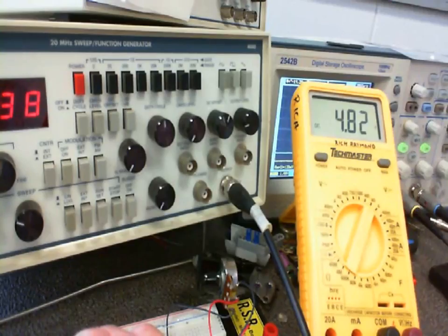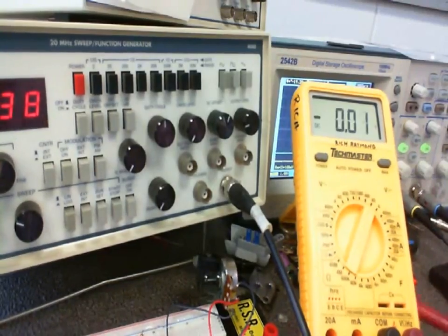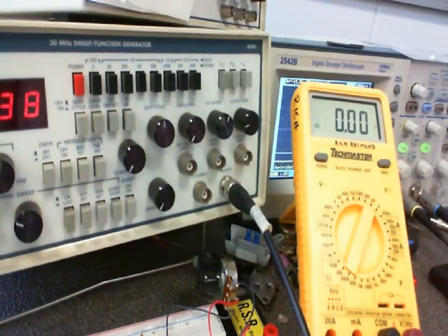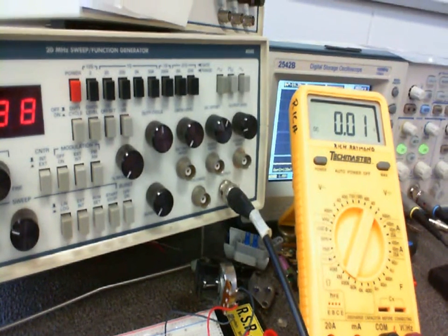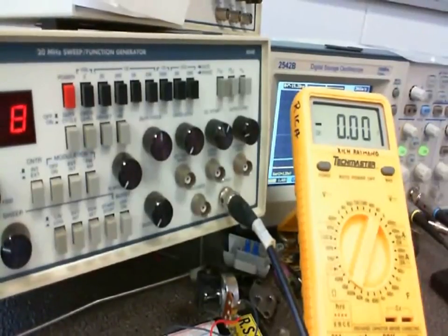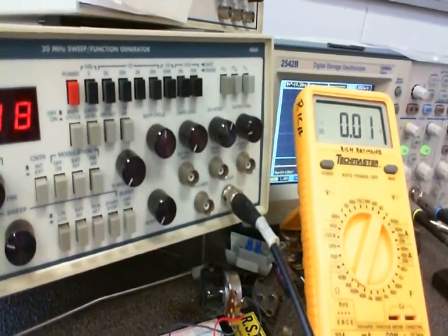Okay. Now what we're going to do is, I've got this heat gun that we use to heat shrink with. And I'm going to look at the collector voltage, which is the collector to emitter voltage, because the emitter is connected to ground, right? You understand? So I'm going to start heating up my transistor. I'm going to take my red lead, put an alligator clip on it, and hook it to my collector.